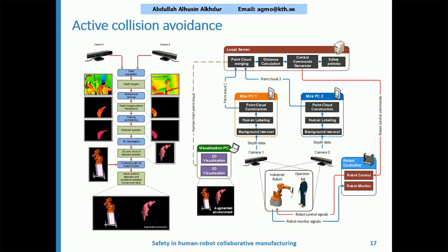And this is an approach we have developed here at KTH Edge that facilitates this kind of collaboration. We have used Kinect sensors as depth sensors, basically capturing the depth information from the scene, determining which are the static parts in the scene, and removing these static parts, considering them as background. Then when the human enters the loop, they will be detected as a moving object, or as a human, with different angles of capturing, which allows us to fuse this information from different Kinect sensors.